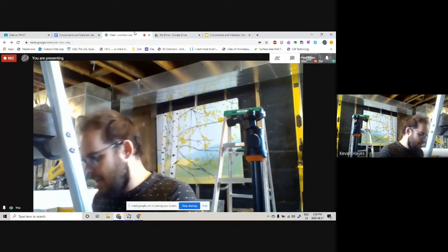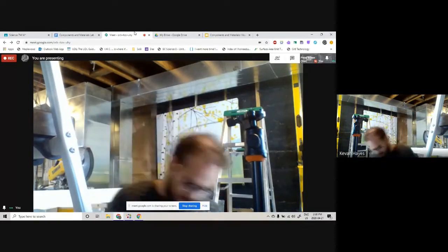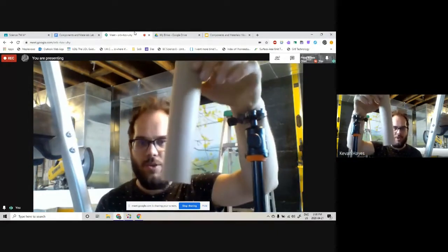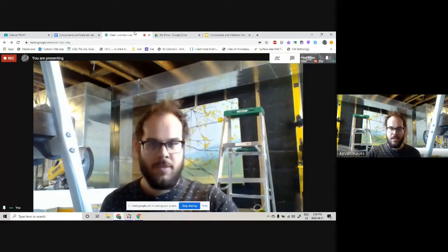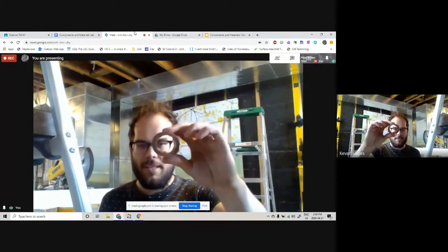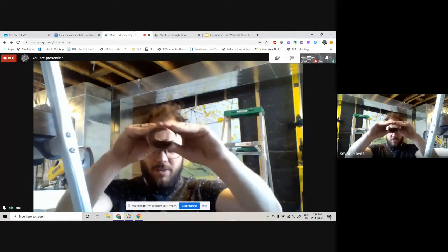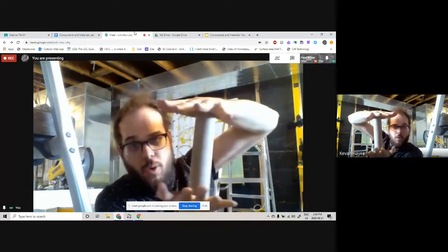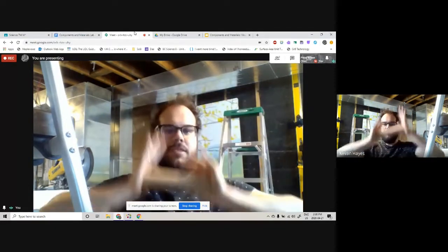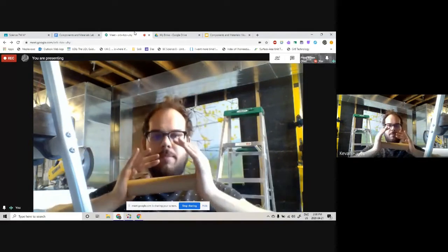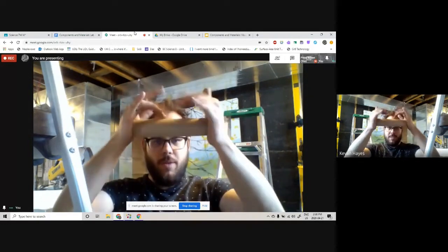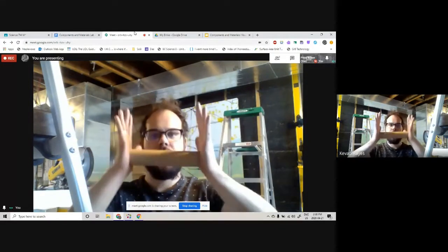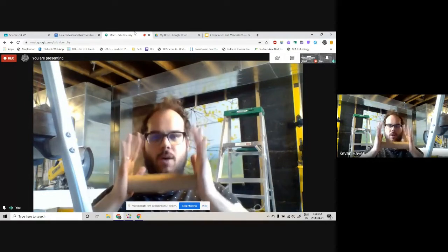This same idea applies if we look at a shell structure. So this is a cardboard tube, which is an example of a shell structure. And with this, it's not very strong this way, right? It goes pretty squishy this way. But this way, it's super strong. If I try to push on this, if I try to put the whole thing under compression, it is very difficult to push this together. And we can experiment with what forces are happening inside of here to allow that to happen. So I'm trying to compress the whole thing. It does not want to compress.